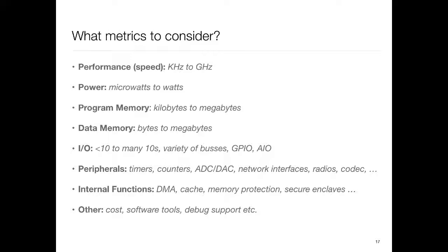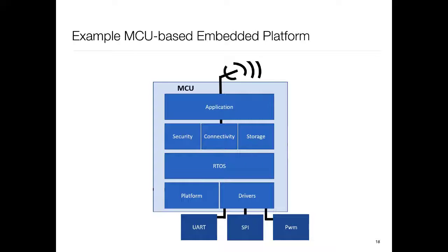So how do you do it? Does it allow on-the-fly changes, over-the-air changes or not? How do you debug it? There is no screen attached to it, so what happens when you do a printf, and all those kinds of things come into play. There are specialized debug devices. So again, that support matters. Oftentimes the processor may be $1 cheaper, but if the tools are awful, then you will pay on the software development side. So that trade-off comes into play. That's the set of metrics to consider.